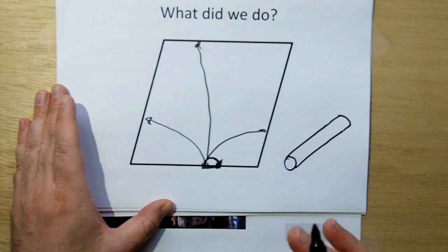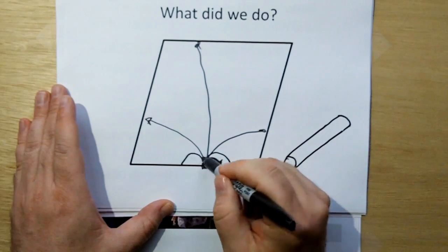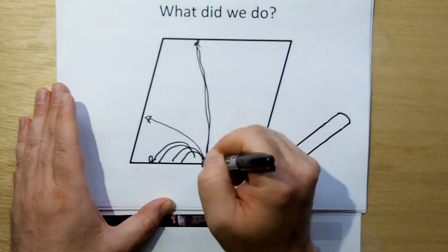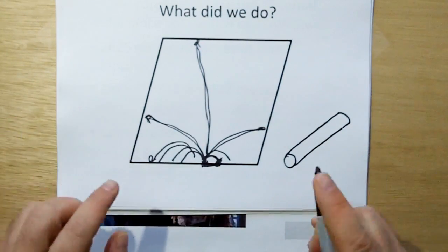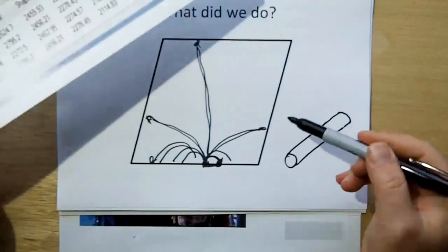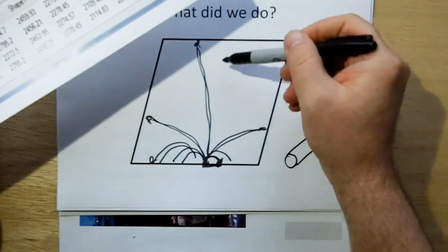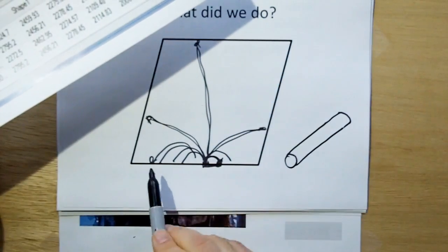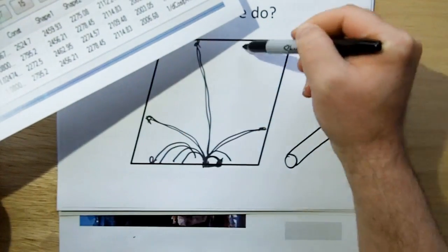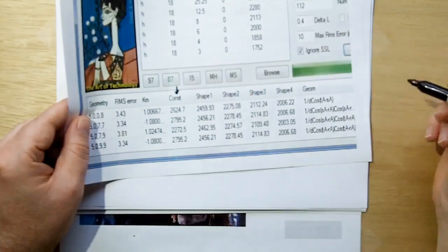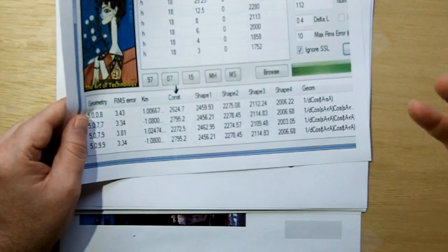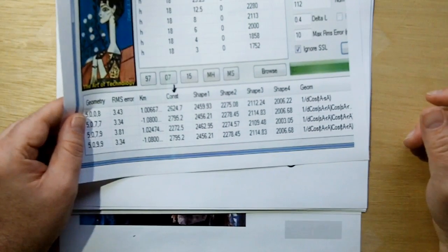So what we're going to do, same side linkage does not compute the fragment to fragment effects within the linear section of wire. It only computes it to the other three sides. Therefore, what's going to happen with the software is the shape effects are just going to be the effects from across space. And what's going to end up in the constant, because the perimeter of the wire doesn't change, the constant in the equation is going to end up being the internal inductance, because that's going to be left over from the linear regression as we talked about before.